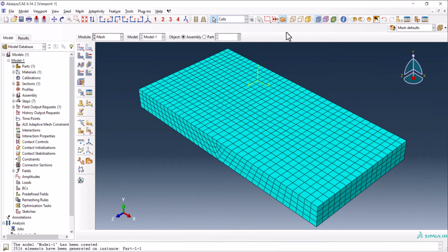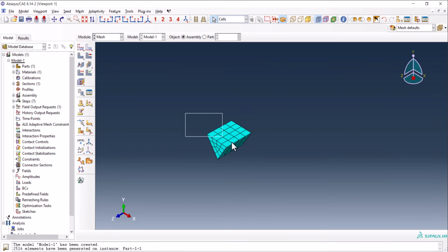So the next thing I need to do is to select this one and select here, replace selected. So we need to create sets and put each of the parts in a set in order to activate them, because it's a birth and death.